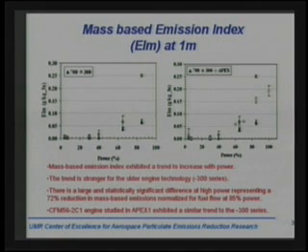And for mass-based emission index, here again, we see that the mass-based emission index, as you might imagine, trends to increase with power, and that there's more mass per kilogram of fuel in the 300 series aircraft. Okay? That is a statistically significant difference, which at high power can mean a 72% reduction in mass-based emissions for the newer technology engine compared to the old.